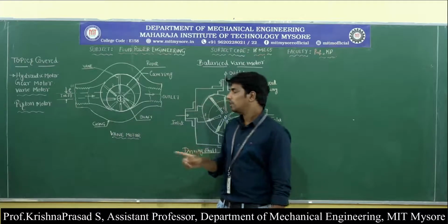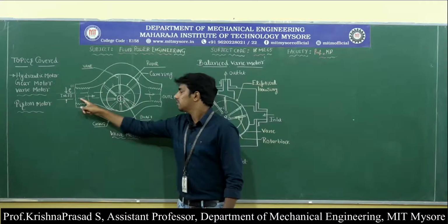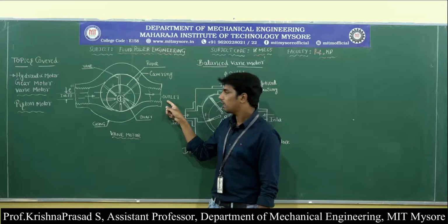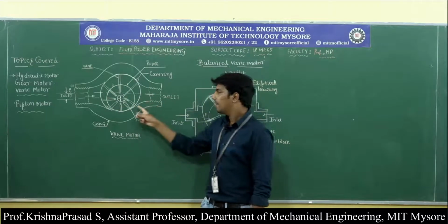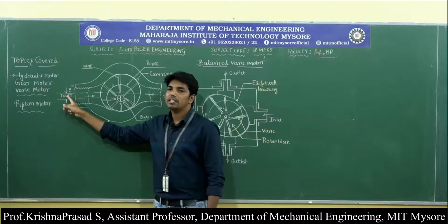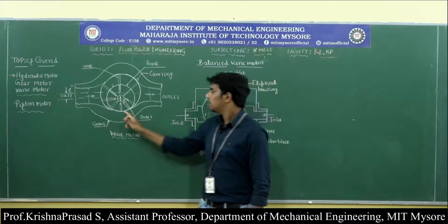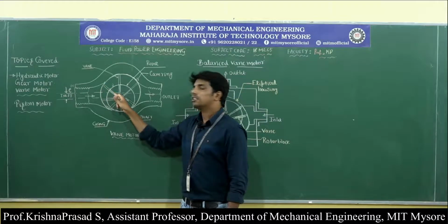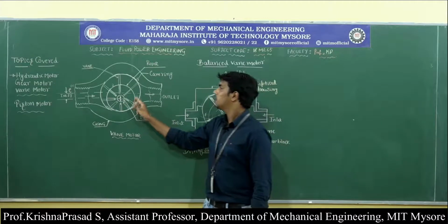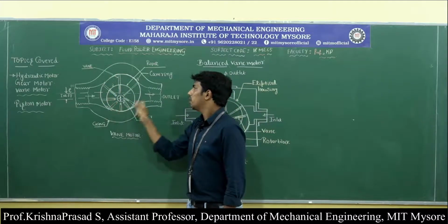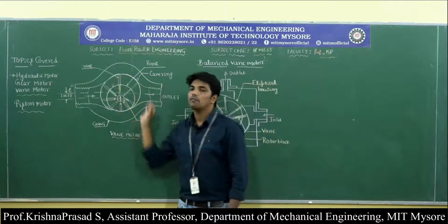Very important, in the vane motor the center line of the rotor and the center line of the camring are not the same, hence eccentricity is achieved. The radial vanes slide in and out of the rotor slot, and they are in complete contact with the camring during rotation. So this is the construction of the vane motor.